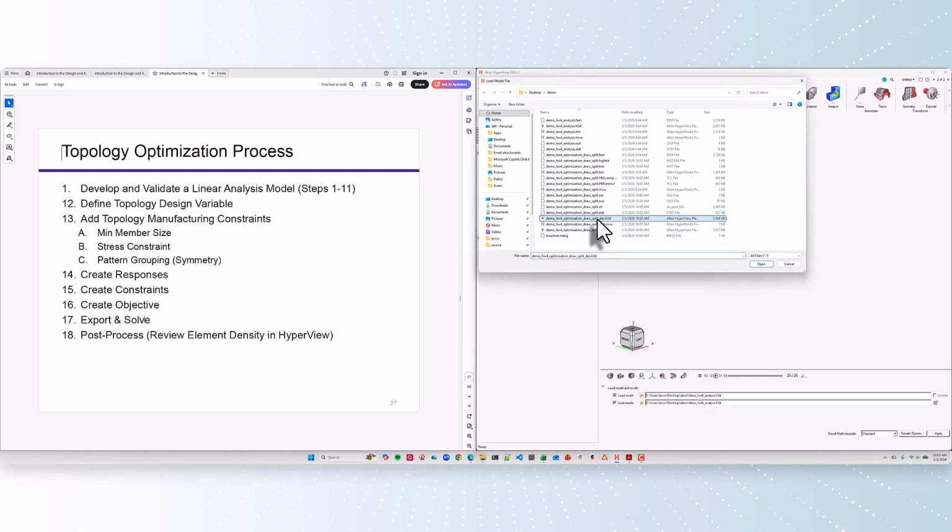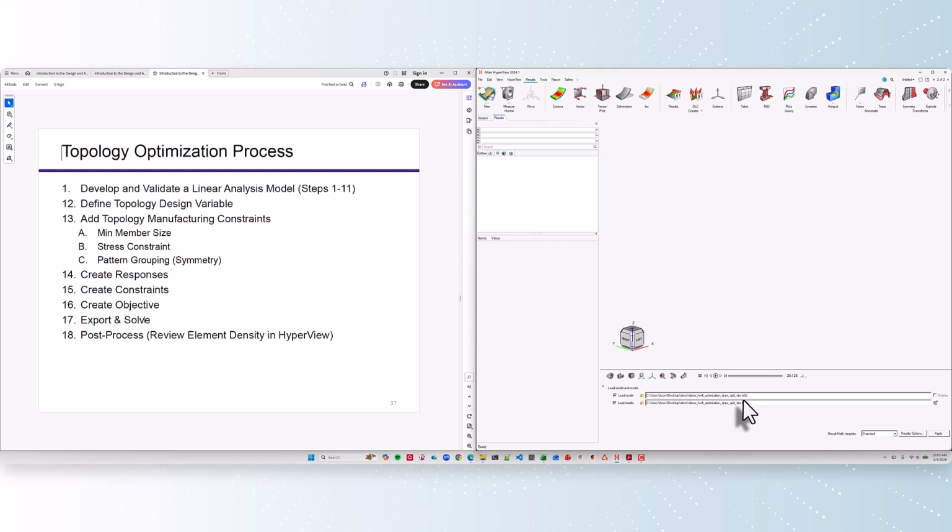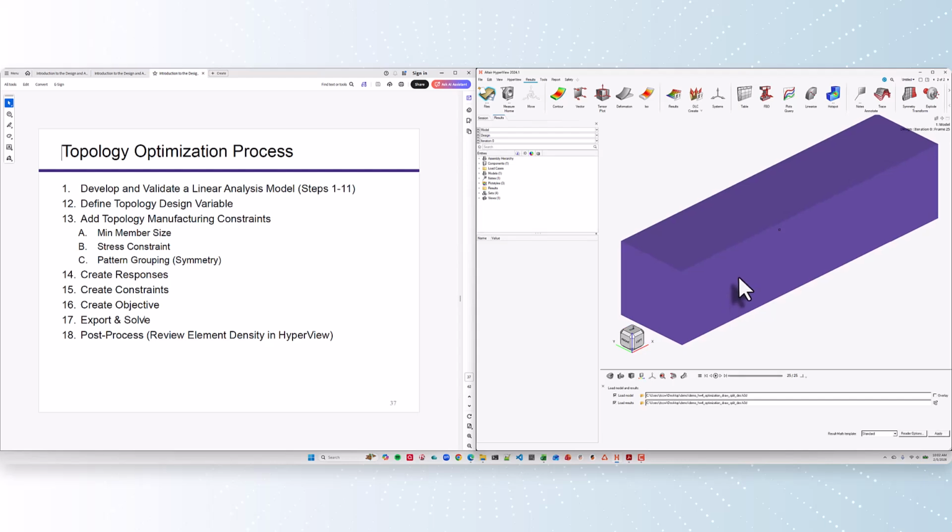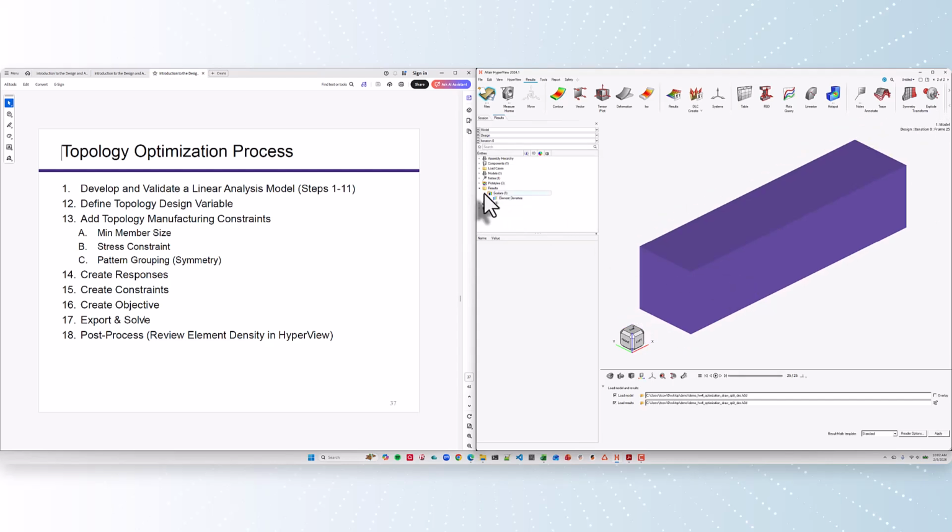variable results. So all of the results in a topology optimization are in the underscore des.h3d, as we discussed in the lecture. So you want to post-process the underscore des.h3d. What does underscore des stand for? Design variables. What are the design variables? The design variables are the density of every element, right? Remember, a density of 1 means the material, a density of 0 means no material.